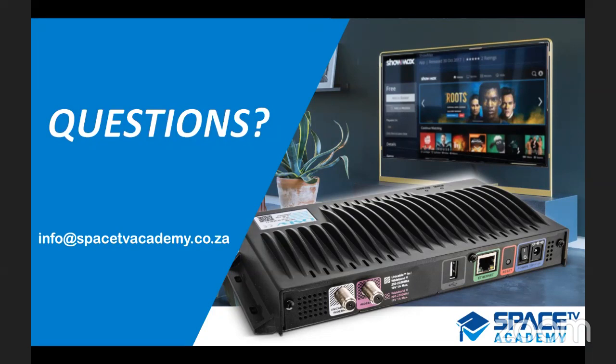Henry is asking, in a SAT>IP installation, why do some decoders display no signal until you reboot the decoder? Henry, difficult to say, but more than likely this could be an IP address issue. When you reboot the decoder, it receives a fresh IP address or a non-conflicting IP address, especially if you're using DHCP or auto IP, which then allows it to be communicated to. Like I said, if I send an email to the wrong Henry address, it goes nowhere. If it hasn't got the right address, it will have no signal, because the server doesn't know where to send the signal to.